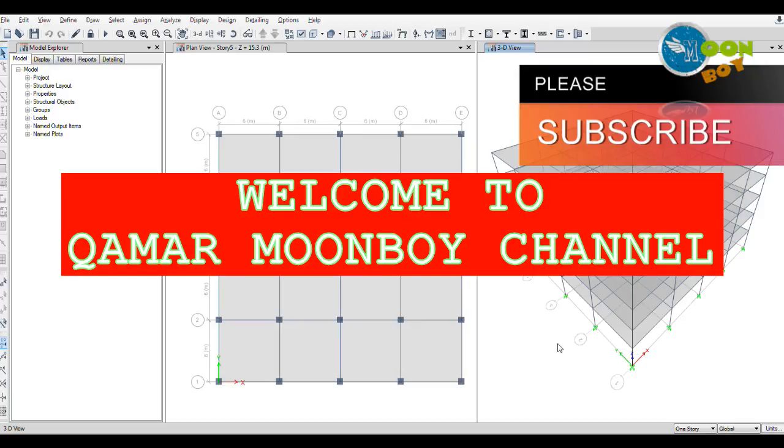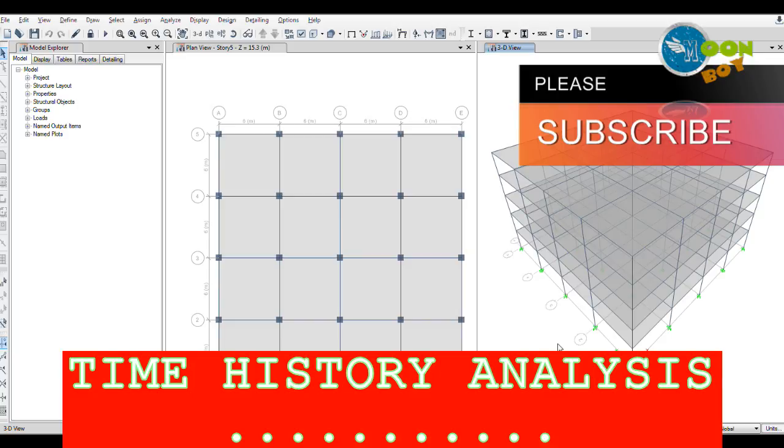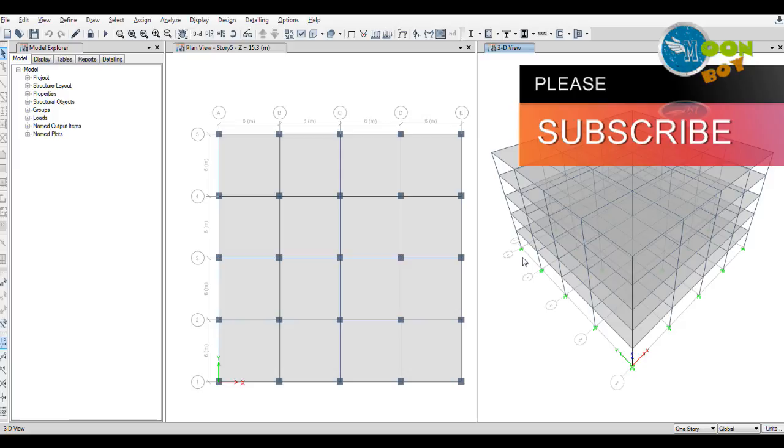In the previous class, we saw how to do response spectrum analysis using the IS codes of Indian Standard 1893. Today we will talk about time history analysis. How can we do time history analysis according to IS codes, what are the benefits and the results, how can we take out the graphs, which earthquake load should we take while doing this, and why should we do time history analysis? All these things we are going to know in this tutorial.